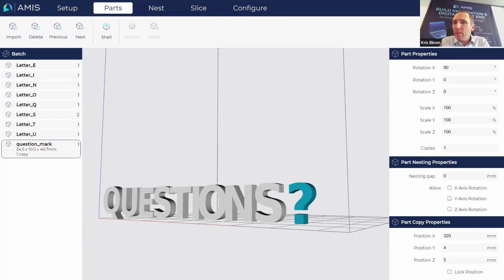But as far as I understood so far, there is no specific need for a specific output from the AMIS Pro software, meaning it would be quite easy to work through a 3MF export and then import into the Formlabs Fuse, by which it can be printed. Of course, if there are faster or better ways, we'll be glad to look into that. But from what I understood, the 3MF export would be rather easy and speedy to get it into the Fuse and get your print out.